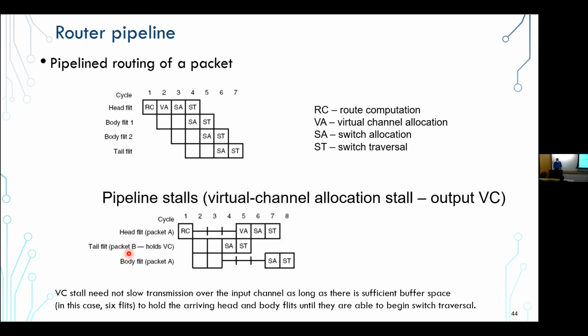For packet B, for example, as it's coming in, it can do on another virtual channel, it can come and go through because its head flit has already reserved all the stuff, right? So it basically has a free pass. Okay. And then, of course, once the head flit A does the virtual channel allocation and traverses, you can basically get the body flit to go through, right?